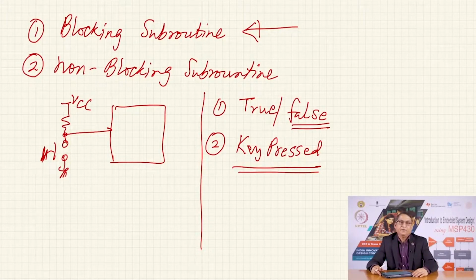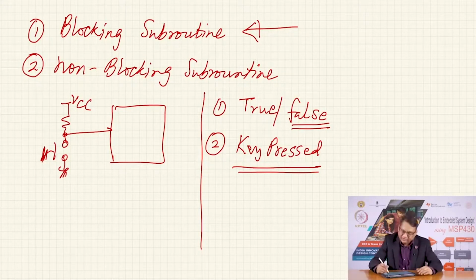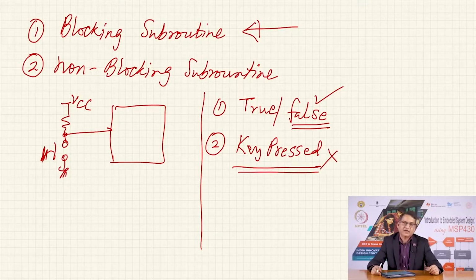He or she programmed the switch matrix and wrote a subroutine as a non-blocking function. So, if you did not press the switch within a stipulated amount of time, it will go back to the main program with the return value set to false, meaning there was timeout, nobody pressed the switch, and the main program will not look at the second variable.